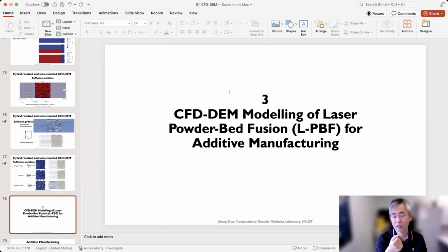Okay, but as I mentioned, for the twisted wire simulations, we just did an approximation and simplified the problem because the wire network itself is big. So at the unit level, we want our model as simple as possible. But collectively, we can capture the collective behavior of the structure response of a twisted wire barrier when subject to this debris flow impact.